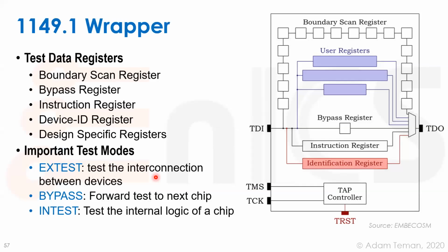Inside this, what you would have in your chip is a wrapper that connects all your IOs together. So you have these inside the IOs. You have to have a register. I will ask Udi and Tzachi, are the registers inside the IO cell itself, or is it a separate register that connects to the IO? It's separate. Okay. I was wondering that, but you have to have a register that's connected to a scan, basically adding scannability to the IO cell.